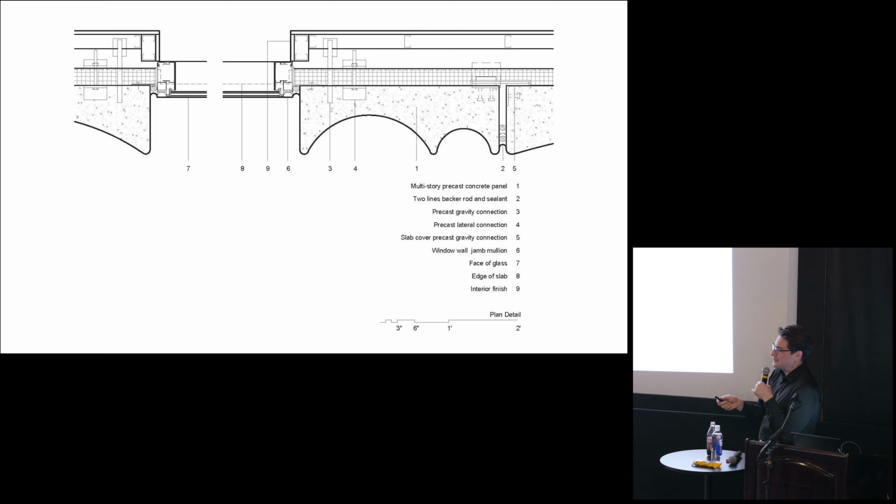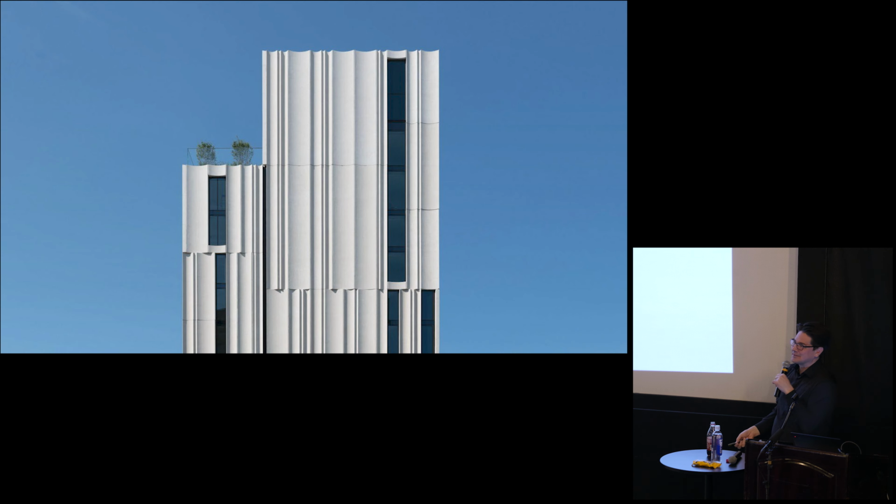So a lot of differential deflection that's taken up in the joint sizes. Students ask, so how wide is my joint? It's like, well, how much differential deflection are you getting? So if you want tight joints, don't do this. But it does look good. This looks like a rendering again.